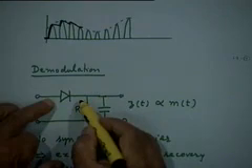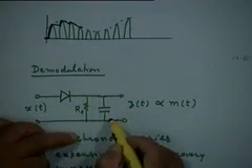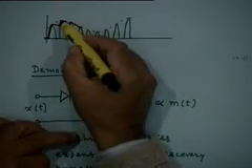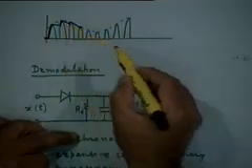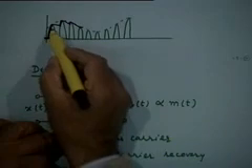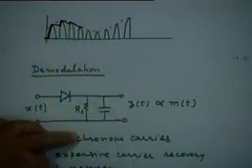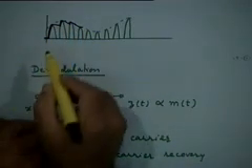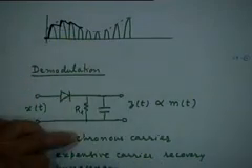At this point again the diode becomes forward biased, again the capacitor starts charging, charges to the new peak value, and this cycle of operation repeats itself to produce an output waveform which looks like the black profile I have shown here, right?